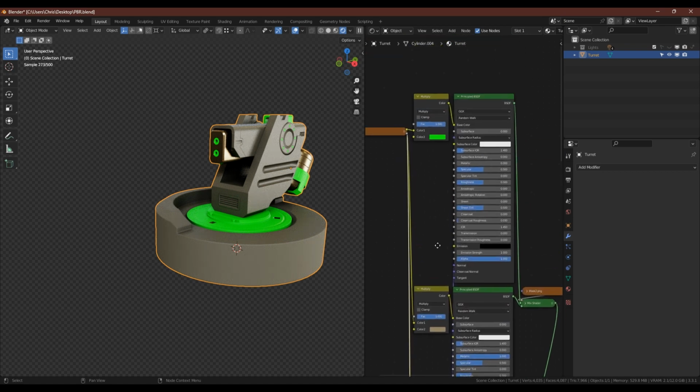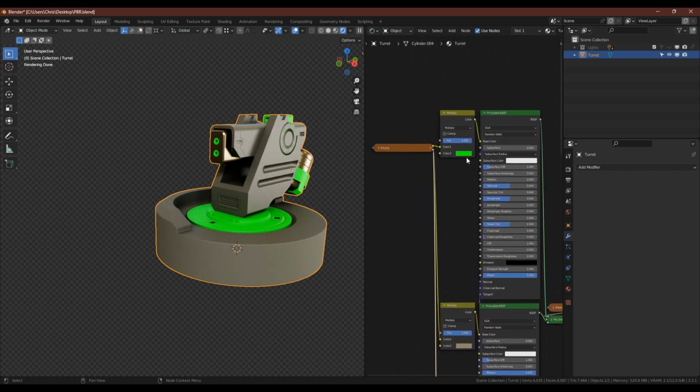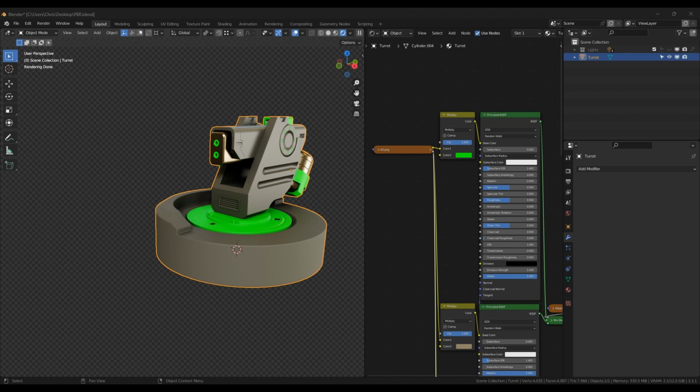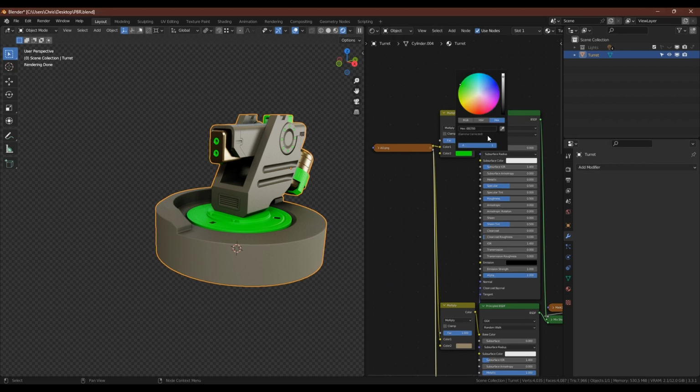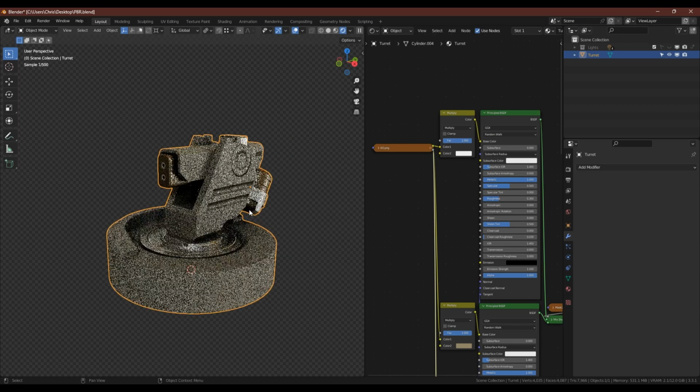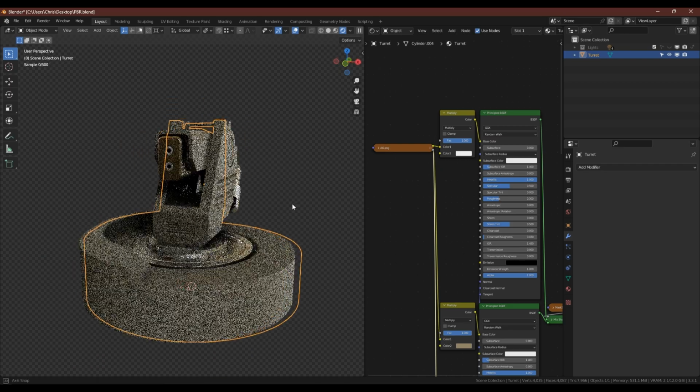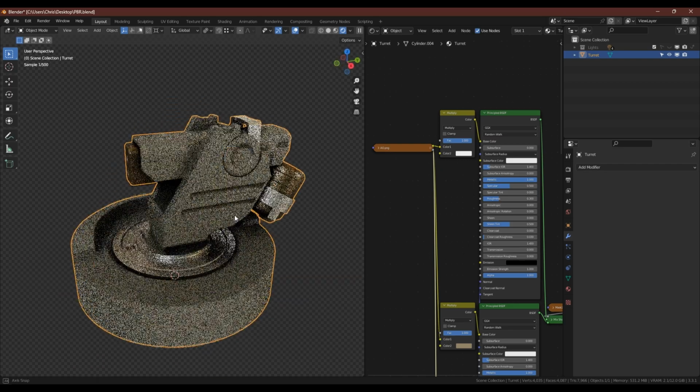And the last part is the metal base. So I'm just tabbing across. You can't see it because I'm only recording the Blender window, but I'm pasting that value, change it to metallic, and drop the roughness down to 0.3, and that's now identical to the high poly that we textured earlier. So we're now ready to begin texturing the model, and I'm going to do that in the next video, as I feel like this is more of a preparation video, so I'll see you there.